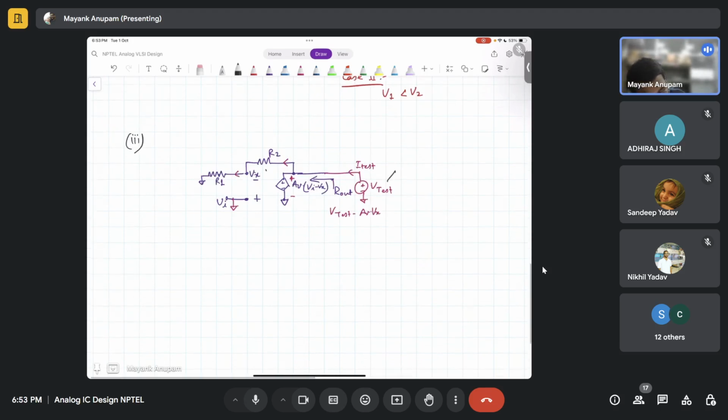This is a voltage source, and this is also a voltage source, and they are connected in parallel. I have shorted two voltage sources. What is going to happen? Huge amount of current. Yeah, this is a catastrophe, right? Unless two voltage sources are equal in value, this is a huge catastrophe, isn't it? Huge amount of current will flow.